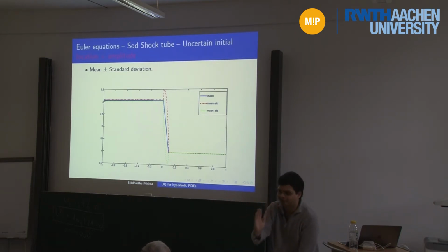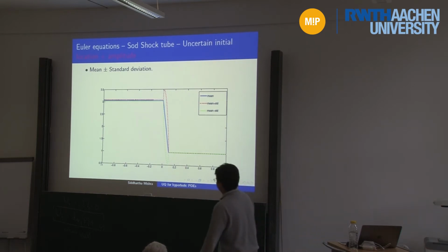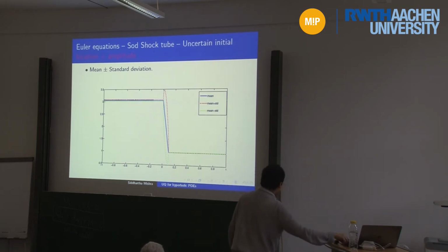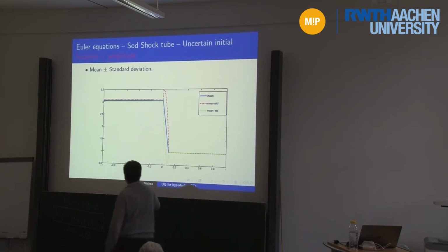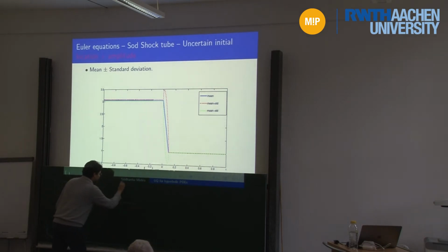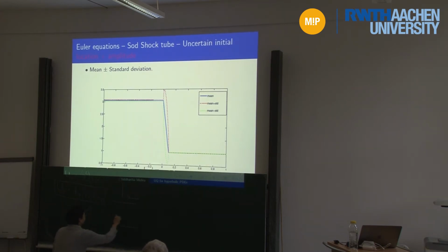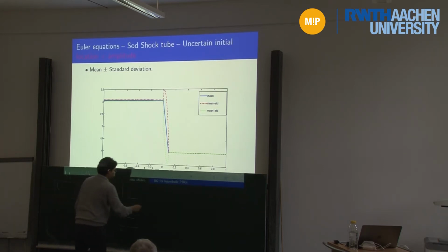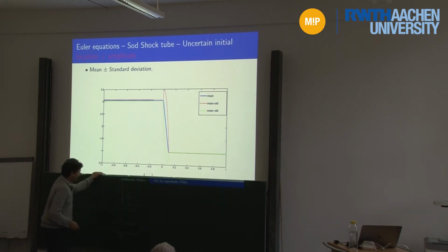So now when you take a one-dimensional cut, this is what you would get initially. I draw a picture because I didn't have it. Initially what you would get is some object like this. So this is the density on the left, the density on the right, then the velocity is 0 on both sides because there is no flow in the beginning, and something with the pressure also. So pressure could be something like this. So this is your p_L and p_R. It's just an example.